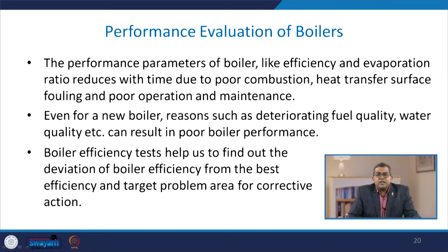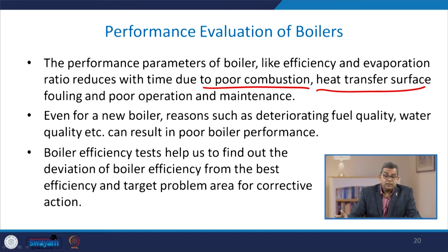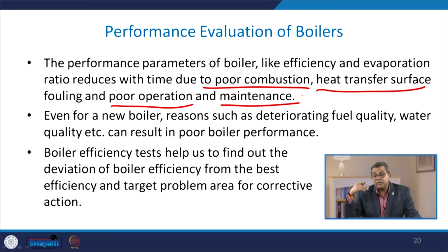Now, these things reduce over a period of time due to poor combustion, maybe because of the wrong choice of fuel, maybe because of low or high circulation of air, etc. Then there may be certain problems associated with the heat transfer surface, which may be attributed to fouling, scaling, etc. This may be attributed to poor operation, very rapid load fluctuation, sometimes leakage, leakage or condensate recovery, or malfunctioning of the preheater.